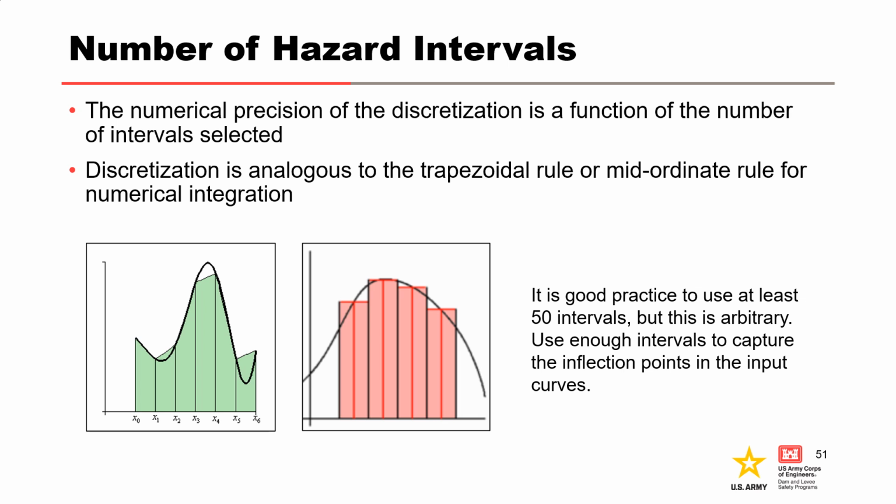With regards to the number of intervals that we need, it's good practice to use at least 50 intervals, but this is arbitrary. The key is to have enough intervals, evenly spaced or not, to adequately account for the inflection points in the input curves.